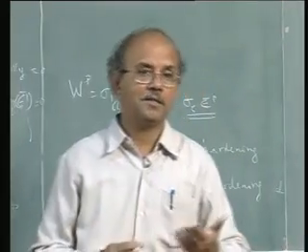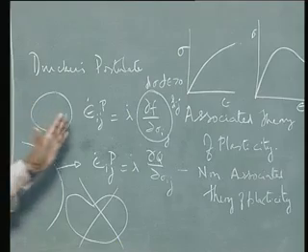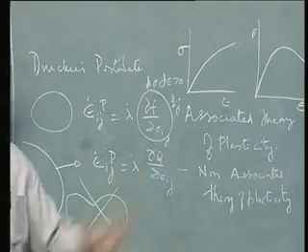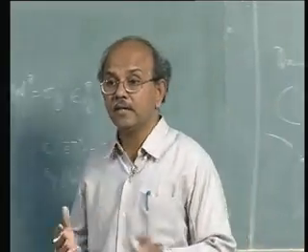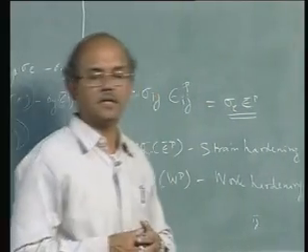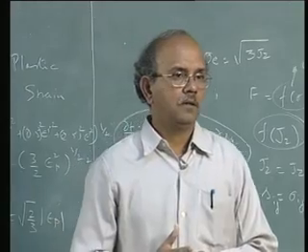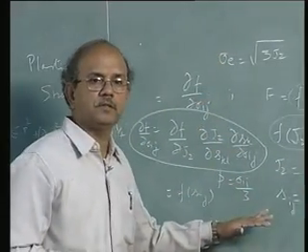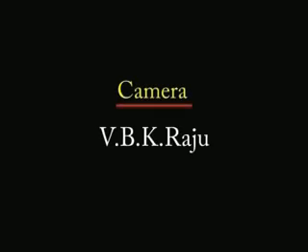In other words, they are in the same direction. The incremental plastic strain and stress would be coaxial. That is a very important result that we will use later. So, with this we will stop and we will continue this derivation in the next class.